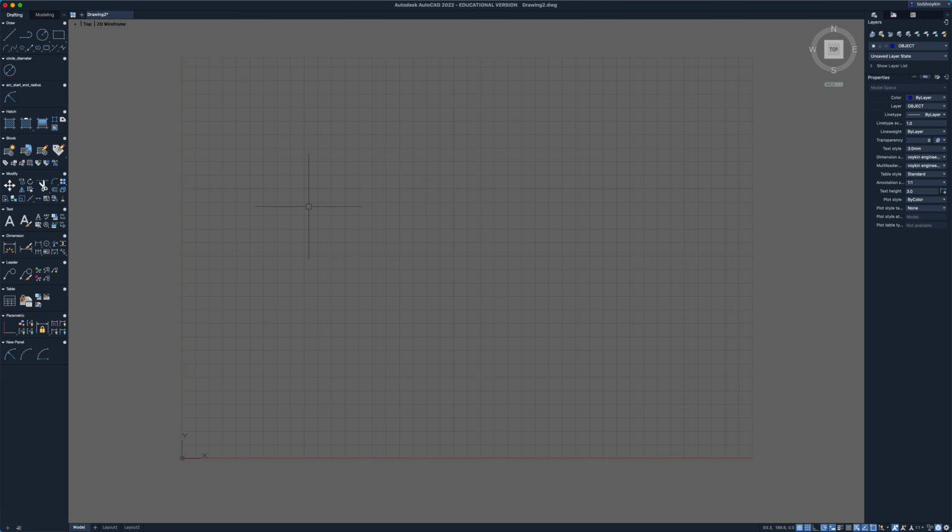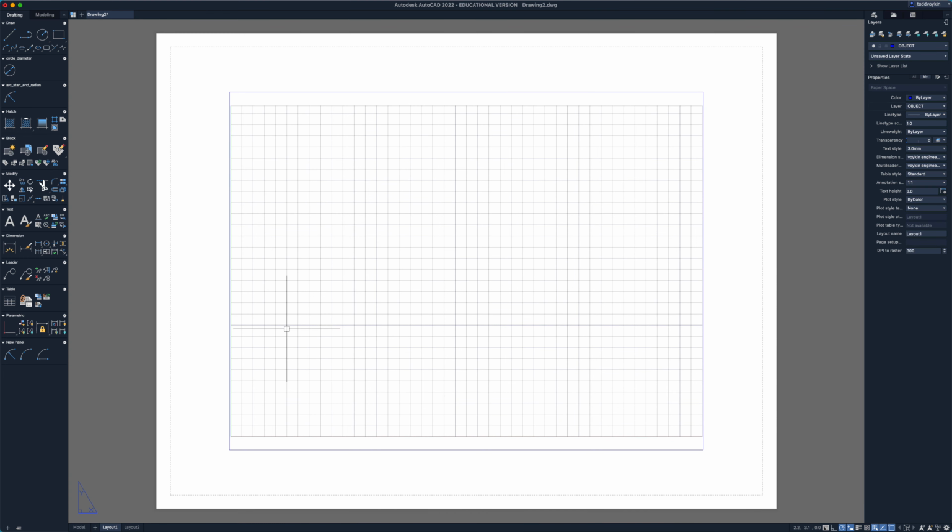Hey everyone, Mr. Voikin here, and we have finished all of the settings that we need to create this template within the model space, but now let's deal with the layout. So down in the bottom left corner of your status bar, click on Layout 1, and that's going to bring up the default paper size, which is not what we want. So what I want you to do is type page, and there we go.